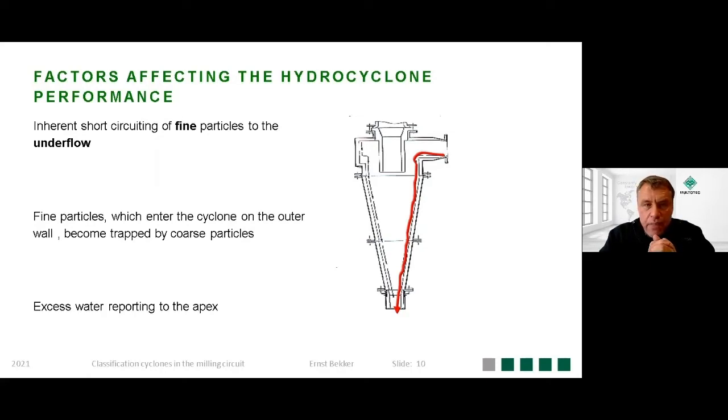That's material that enters into the cyclone and is then positioned against the side of the hydrocyclone. It migrates all the way down and leaves through the underflow. So some of the mechanisms: entrapment, where the material cannot pass through the layer of material in front of it. That's also quite applicable when you've got very dense separations or dense slurry densities inside the cyclone.